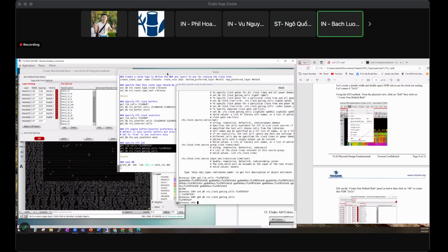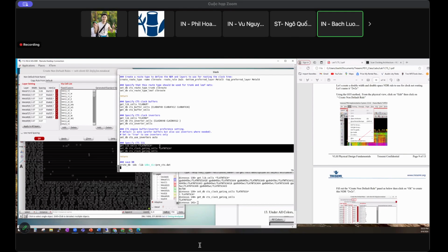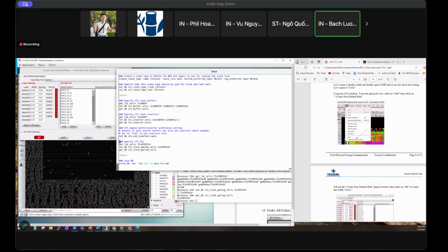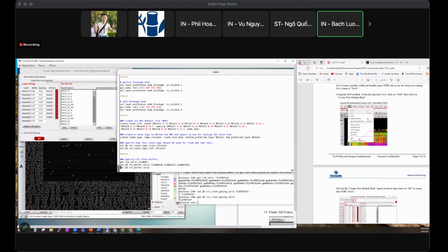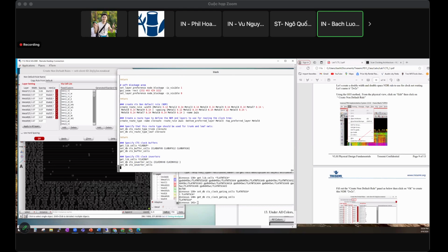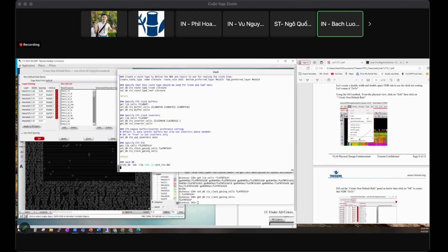Okay, so in terms of the clock trees, we just constrained, right? We tell the buffer inverters the layer, and the NDR, we applied it. So that's really the part of the clock tree that I stop here, because we create this, we set some of the NDR rules, and then we haven't got to the... So this is where we stop in the lab. I think in the next lab we start with the clock tree spec and we actually start to build a clock tree in the next lesson and the next lab.